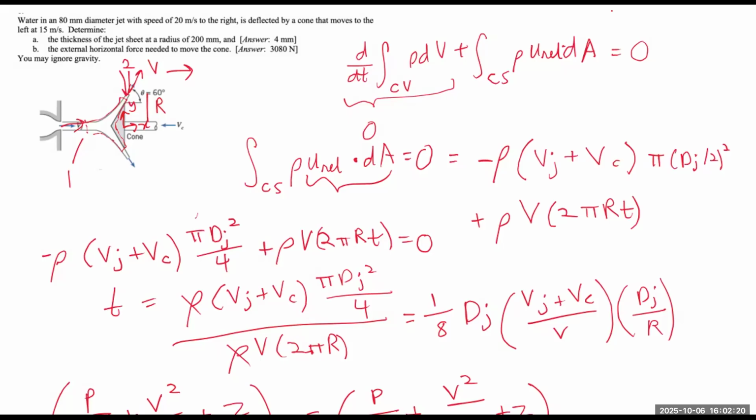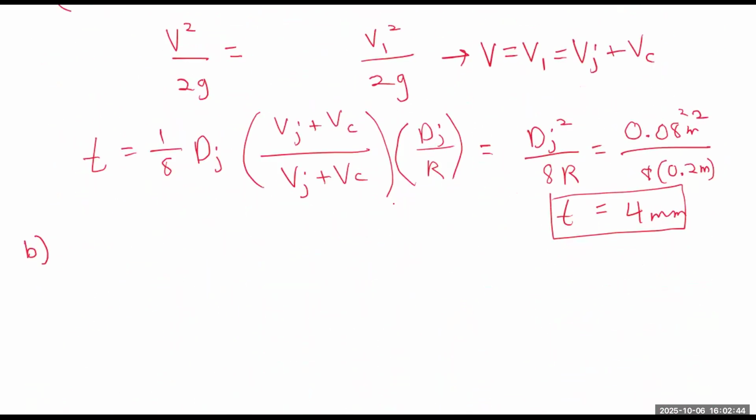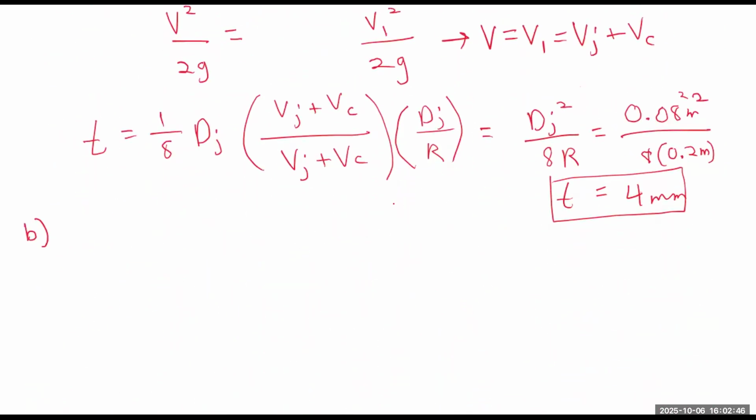Basically, since we are able to model the flow as steady state, one of our integration terms disappears, which is very nice. And if we had not assumed steady state, we would not have been able to apply Bernoulli's equation to solve for this V over here. But for part B, an inertial reference frame is more beneficial.